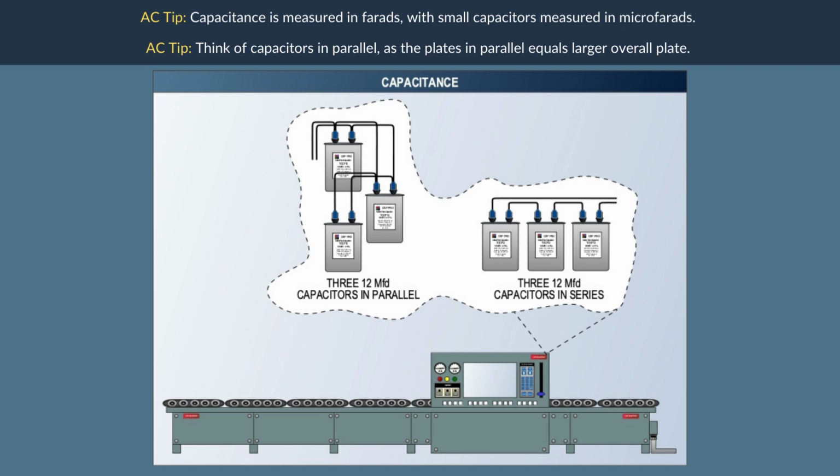to a negative charge. The unit of measurement is a farad, with small capacitors often measured in microfarads, or 0.000001 farads. The symbol of microfarads is MFD. A capacitor with a maximum amount of electrons is considered to be charged. The surface area of the plates, the distance between the plates, and the dielectric material between the plates are all factors that affect the capacitance of the circuit.